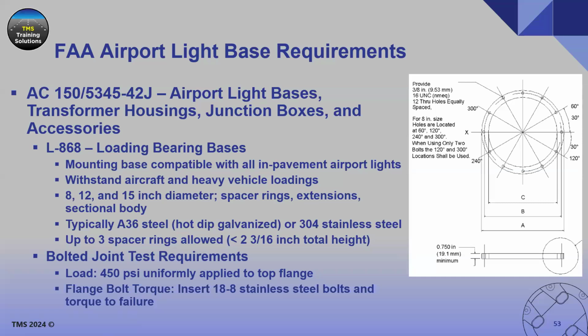Now, there's a lot of qualification tests for base cans. I pulled out a couple that are related to how the actual bolted joint works. So the first one would be the load test that's performed on the base cans, which is a 450 PSI applied to the top flange to check for deformation or movement of the flange under that loading. So that would simulate an aircraft rolling over or sitting on top of a base can.